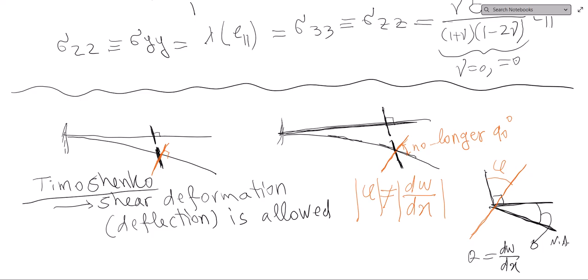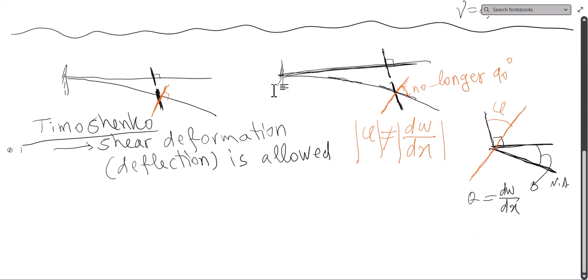You remember that in the previous video I mentioned that when the slenderness ratio of the beam, which is the length over a typical dimension of the cross section, becomes smaller and smaller, then you cannot ignore the shear deformation, or the effect of shear stress and shear strain, of course. Therefore, if you get such a situation, this is what is happening.